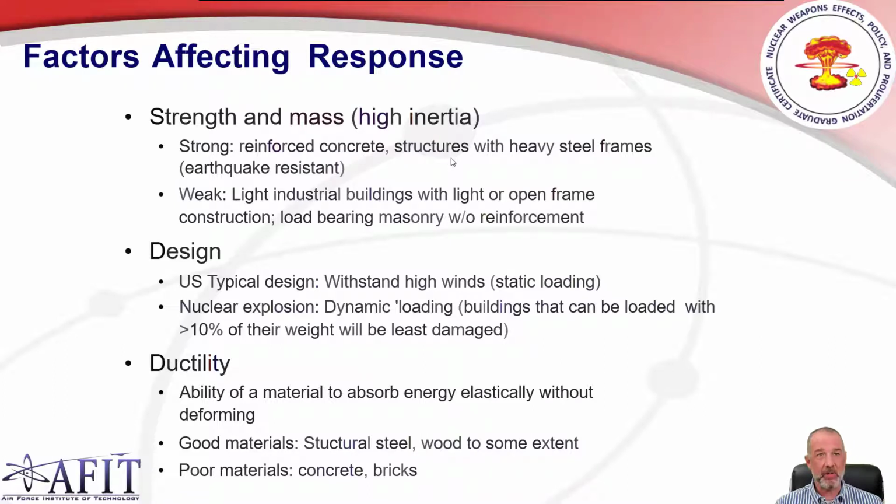Mostly military structures, command and control, continuance of the government, bunkers, that sort of thing. And these were built to be able to handle both that overpressure and a dynamic pressure without suffering any harm. And this has to do with openings that are covered with materials to not allow that overpressure to work its way into the building to further cause damage, and to avoid being squeezed or pushed over.